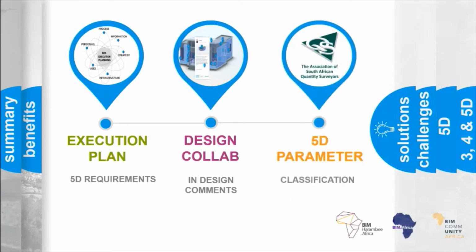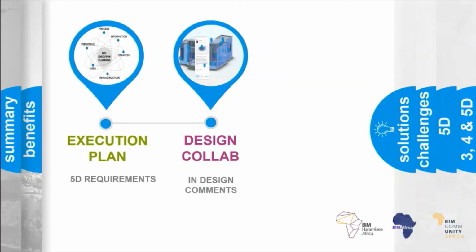And well before a quantity surveyor can apply a parameter to the model, or apply a classification code to the 3D model, we, as quantity surveyors, should be contributing to the development of the model through a common data environment that allows for collaboration and commenting on the progressive development of that model. We recommend that quantity surveyors be invited to a cloud-based system, such as BIM 360, and that the quantity surveyor must undertake a review of the model at appropriate intervals in order to comment on the geometry of the modeled objects and the parameters applied to them.